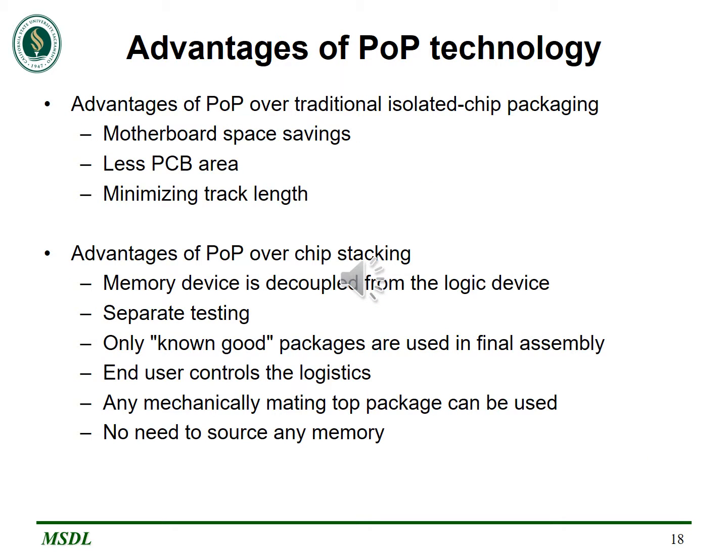Next, we are going to discuss the advantages of using package on package semiconductor technology. The most important advantage of using this semiconductor over isolated chip packaging is that it allows us to save more motherboard space. This package-on-package semiconductor uses much less PCB area, almost as little as stacked die packages. Electrically, package-on-package semiconductors offer benefits by minimizing the track length between different interoperating parts such as a controller and memory.